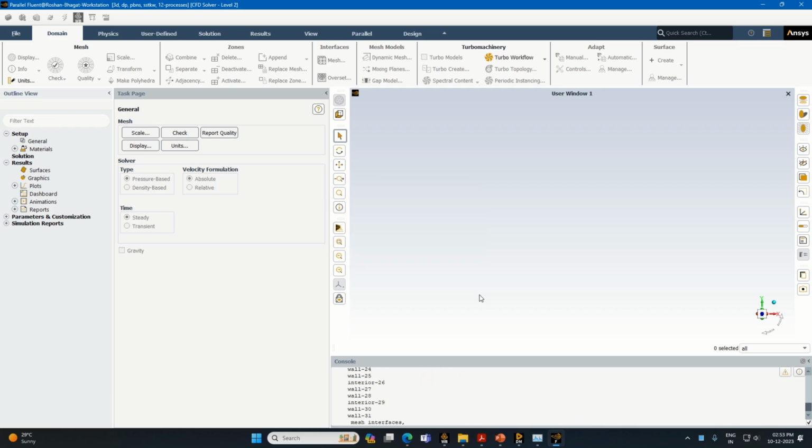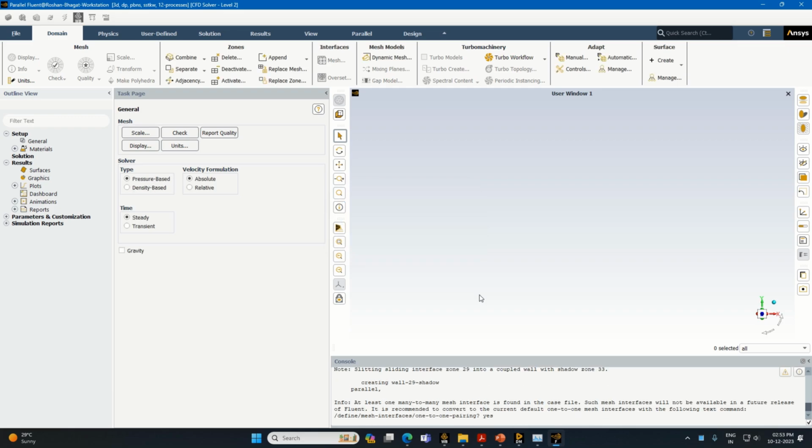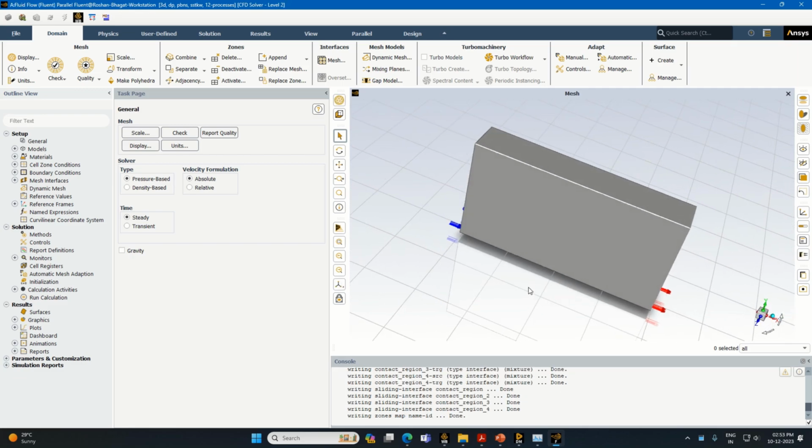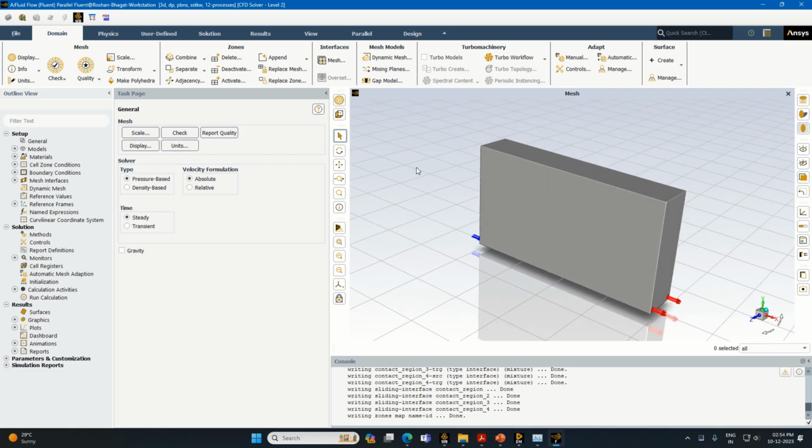As we have taken the finer size, it will take some time to load all these things. So you can just check out the arrows if they are in the proper direction or not. This is a very important task. Select the transient model time, then we say minus 9.81 over here as gravity.